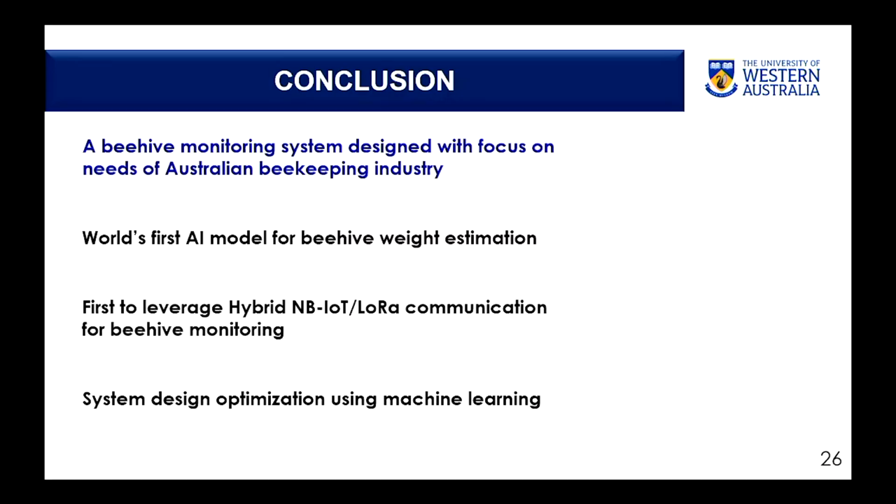I do a CRC checksum. If there is a communication error or something happens and the CRCs do not match, I discard the data. But if the CRCs match, that means this data is okay. Just dump that binary data into a file. When NB-IoT wakes up, it reads that binary data and transmits it via MQTT to my server. No translation required at all.